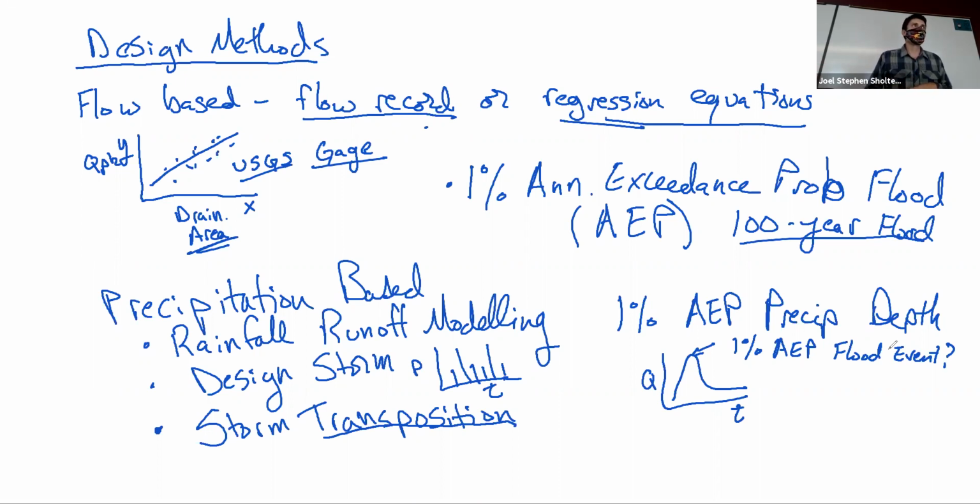The flood frequency analysis of a particular stream that drains a watershed that a rainfall event comes on is obviously related to the magnitude and frequency of rain that the watershed receives. But there's a disconnect between what we observe in rainfall frequency and what we observe in runoff peak discharge frequency. There are a lot of reasons for that.